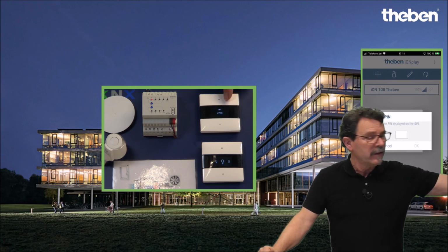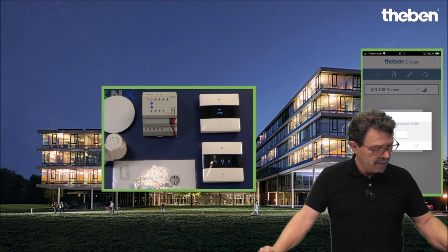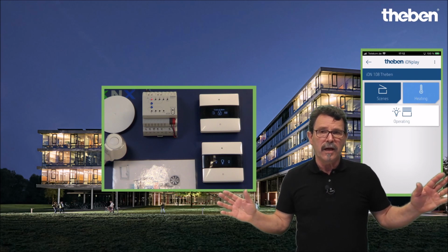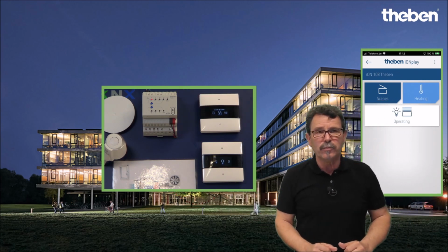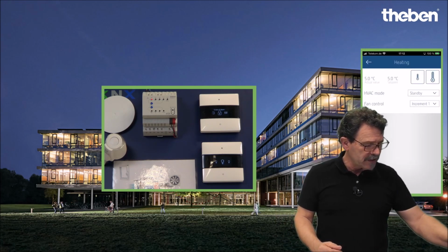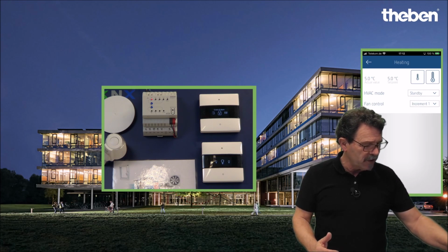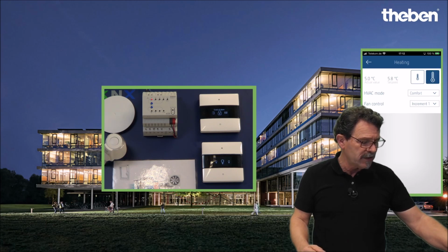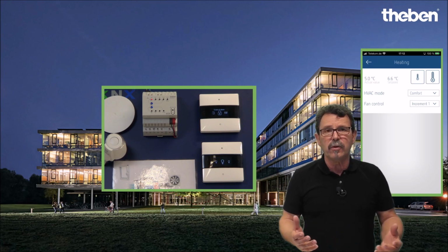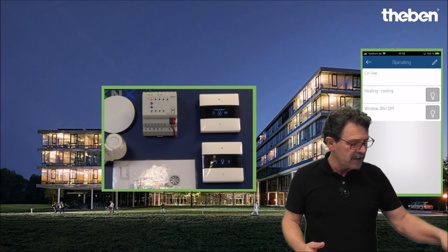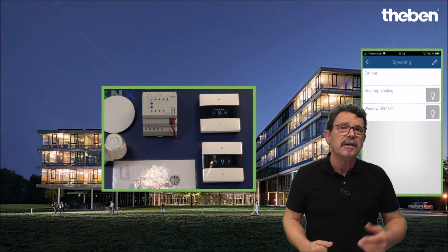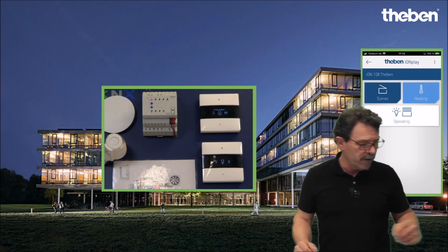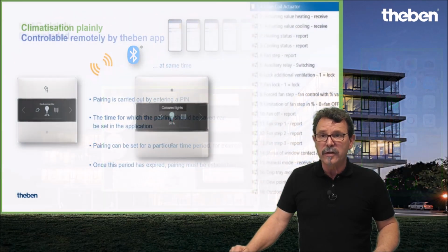And now you have the discovery that the controller here is giving you a Bluetooth pin code. In my case, it is 4700. Okay. And then automatically, I have mirrored the function from this nice room temperature controller directly on your app. And you can open the app, can modify the fan control, can modify, in this small example, the modes, different modes from comfort to standby and so on. And for instance, you can modify the set point temperature, whatever you like, remotely. If you have programmed some further functions, you then get listed here, it takes a second, the CO2 values, humidity or whatever.